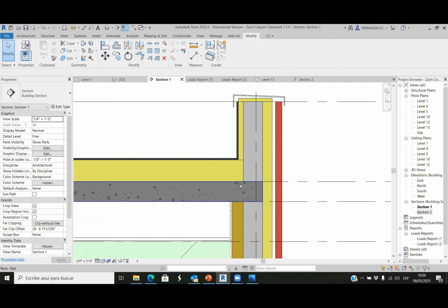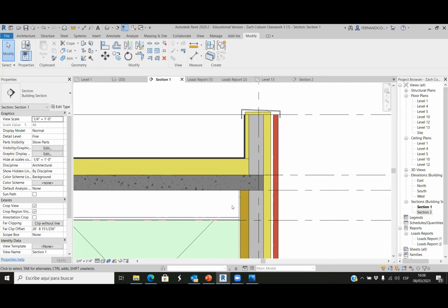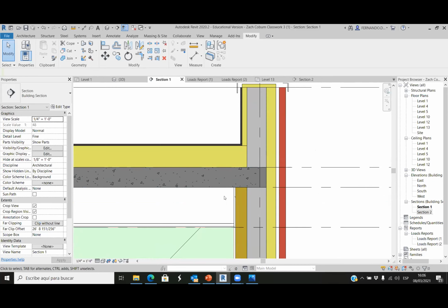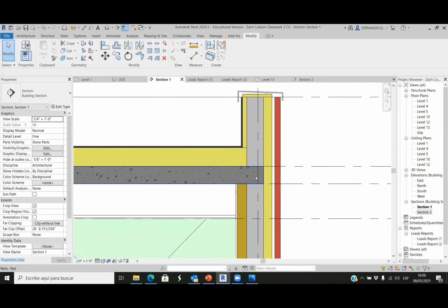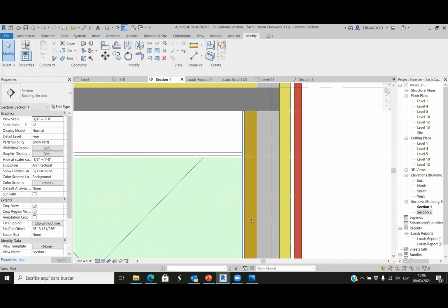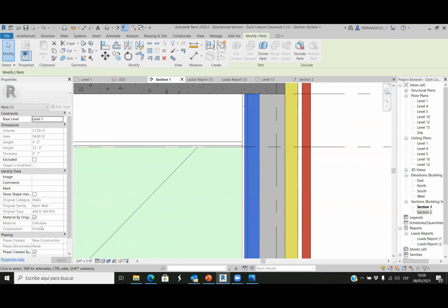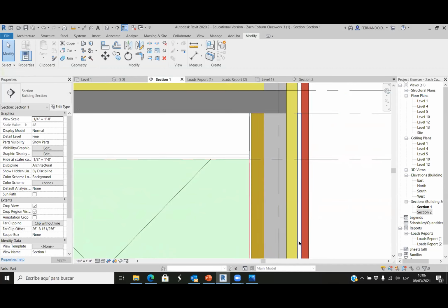Okay, and now I told you that we are going to do the same in THERM. Because in THERM, we have to analyze whether we have a thermal bridge, because here, if the heat tries to go this way, we find the thermal insulation here. But now we can quantify how much heat we are losing through this, because this is the weakest point of this detail, because the wall is well protected, because we have 7 inches of cellulose here, and then 6 inches, so 13 in all, of thermal insulation.